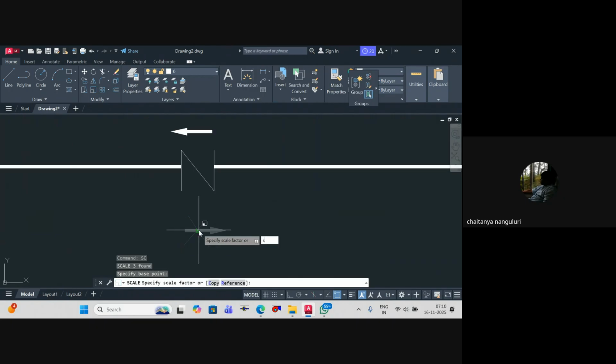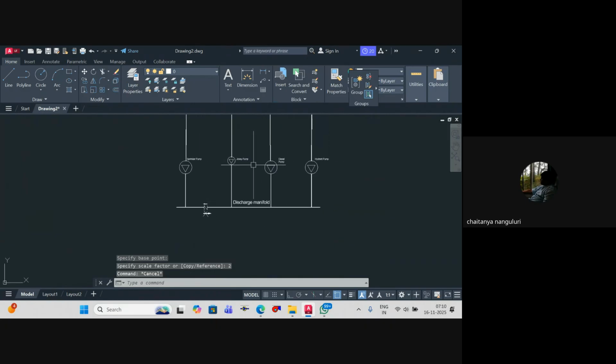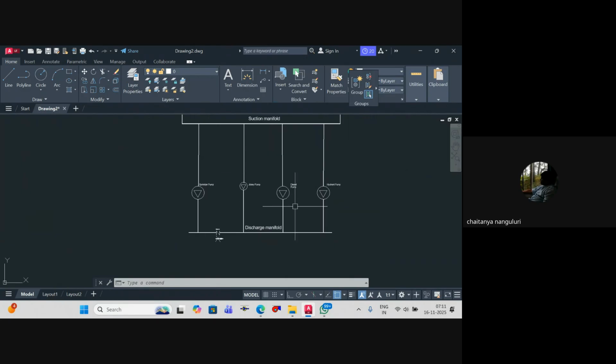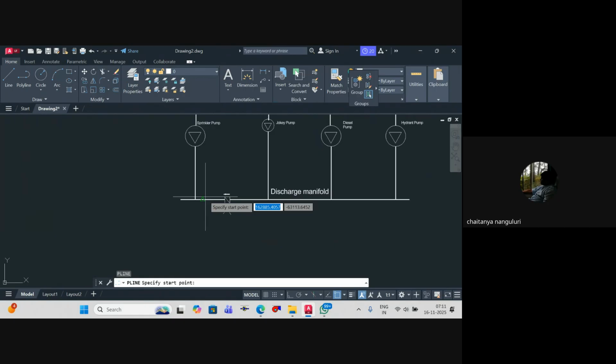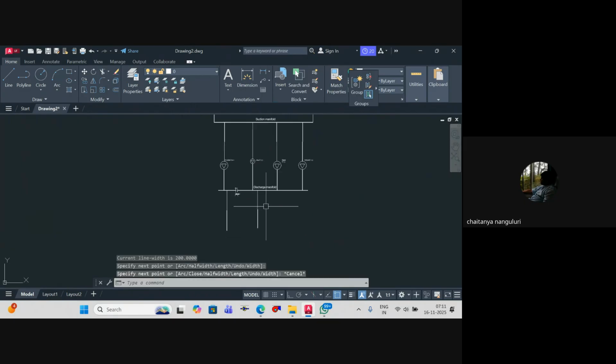Because once the firefighters come into the picture, they will be able to manually switch off the sprinkler pump and the entire water will be used for the hydrant system. But until fire rescue comes into the picture, your sprinkler plays a major role. You agree? So for that reason, it's mandatory for the water to flow through this to the sprinkler system, but not to the hydrant system. So from here you will take a tap to your sprinkler network, and this you will give to your hydrant network. This is to the sprinkler system. This is to the hydrant network. Am I clear?